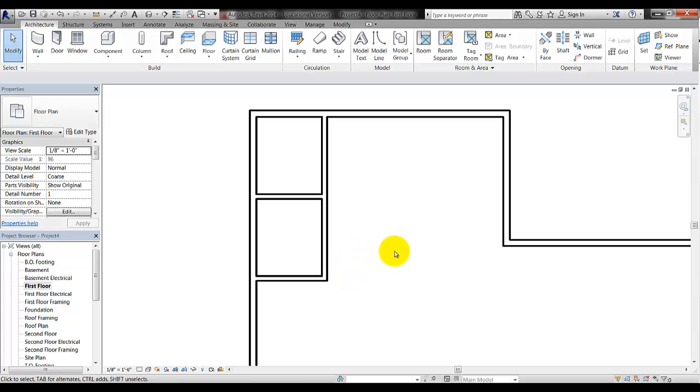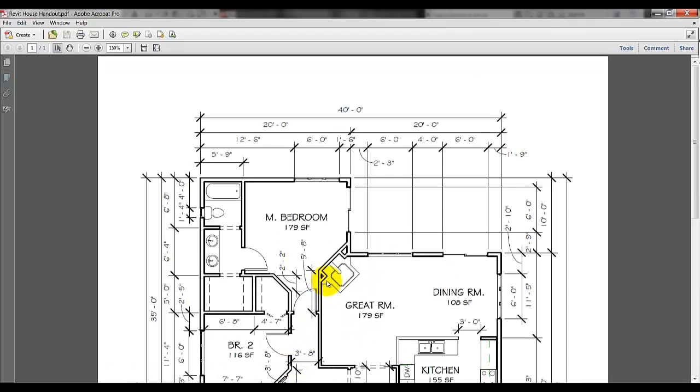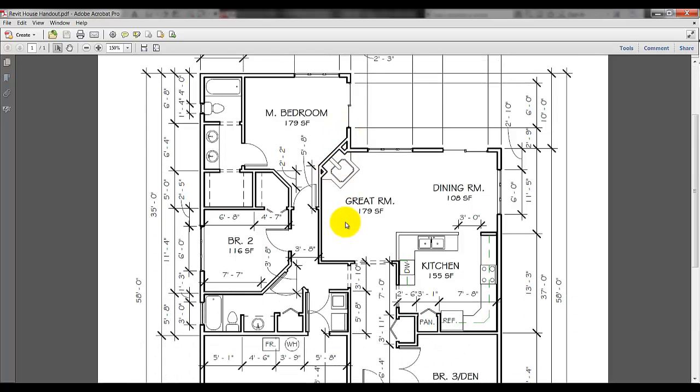So you can continue to work through creating these interior walls throughout the plan. There are some places where you might find it's a little bit of a challenge to find them. Pay attention to the dimensions on the drawing. Take a look at whether the dimension is coming from the inside face, the center line. Here's another one to the inside face. In some places you'll notice that they go to points. So this is to that corner. This one's back to the center line. This one here is also to the corner. Just note that, pay attention to it.